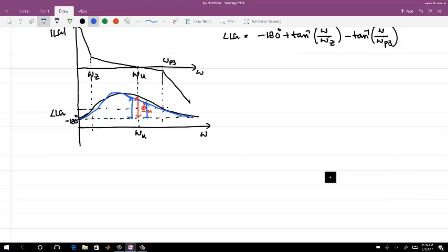So do you see any problem, or what better can be done? So let me just say, in the previous red curve, your unity gain frequency and your phase were not at the peak of the phase value. If suppose the unity gain frequency was here, then your phase margin was this, right? But you are not on the peak, you are somewhat away. So is there anything you can think of that can be done better?